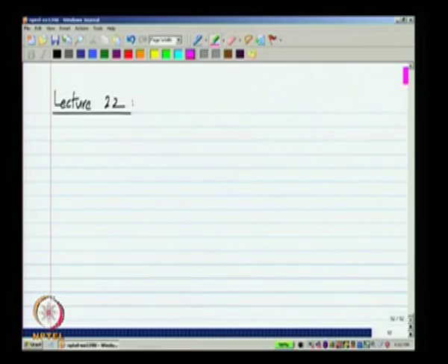This is because the bulk and the gate are similar in a MOS transistor, they play similar roles. In an NMOS transistor, increasing the gate voltage or the bulk voltage increases the amount of charge in the channel and leads to an increase in the current. Modeling the effect of the bulk is quite important in a MOS transistor, especially on an integrated circuit.